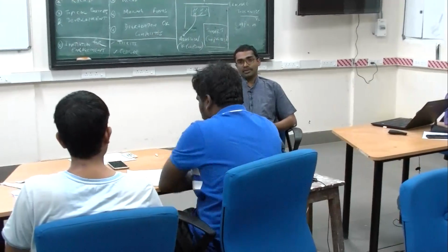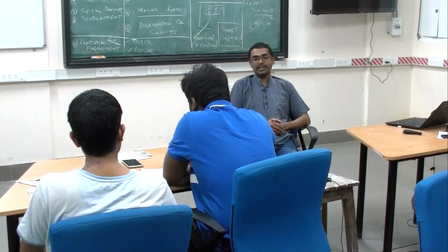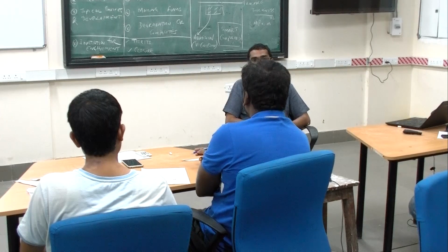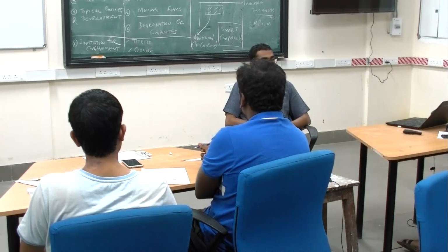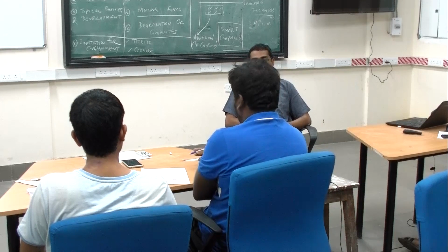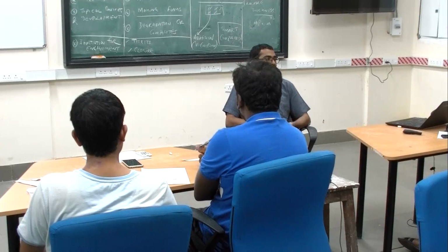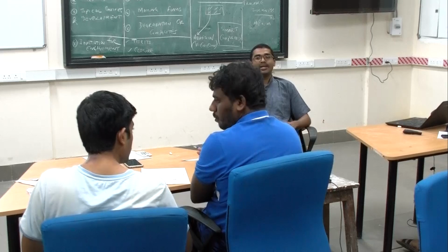Mechanical. What mechanical property? Elastic modulus. So you are thinking about Young's modulus. So the rule of mixtures would be XA YA plus XB YB, correct? Where XA and XB would be the mole fractions. What is XA plus XB, by the way? 1. XA plus XB will be 1. So I can equivalently write it as XA YA plus (1 minus XA) YB, isn't it? Alright. And that is because that is how mole fractions are defined, right? The sum of mole fractions is 1. Okay.